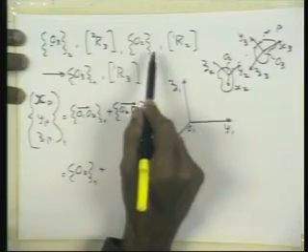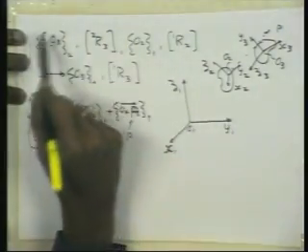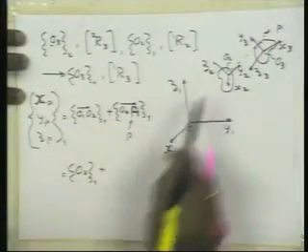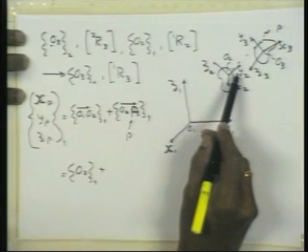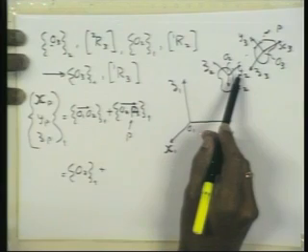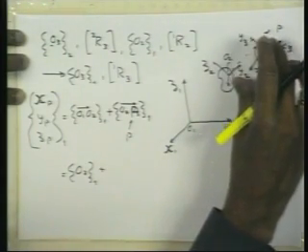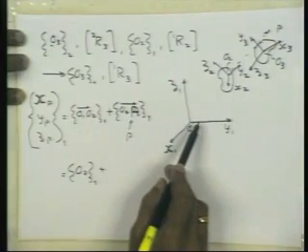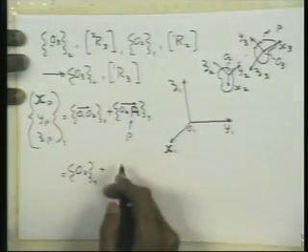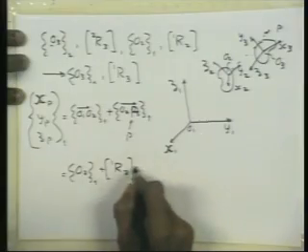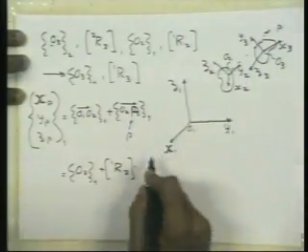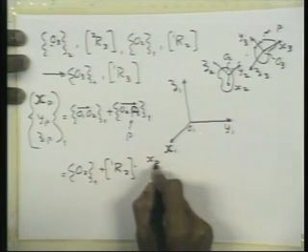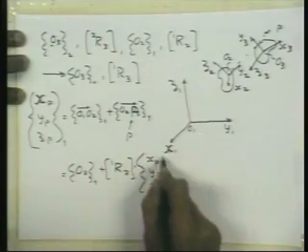Now we can use this transformation. We can use the position and orientation of this body with respect to this body to find out the position of P in this reference frame. That is, and then we can, one moment. Okay, this is this vector. If we consider this vector in the second reference frame, we can transform it to the first reference frame. Right? We are considering it as a free vector. So what do we get? We have R2 with respect to 1 multiplying the position of P in this reference frame. That is xp, yp, zp in reference frame 2.